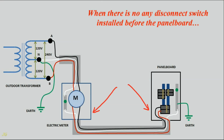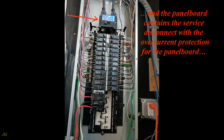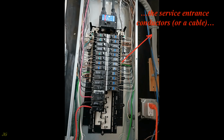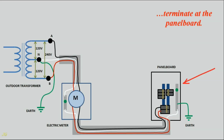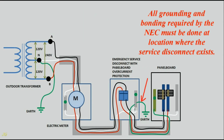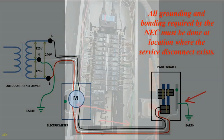When there is no disconnect switch installed before the panel board, the panel board contains the service disconnect with the overcurrent protection for the panel board. The service entrance conductors, or cable, terminate at the panel board. All grounding and bonding required by the NEC must be done at the location where the service disconnect exists.